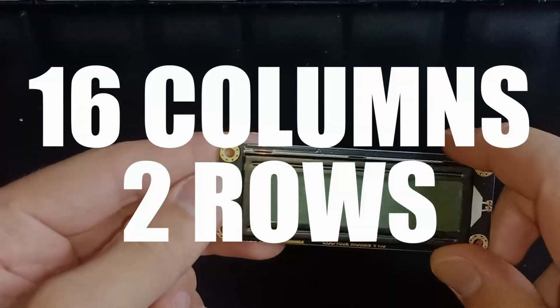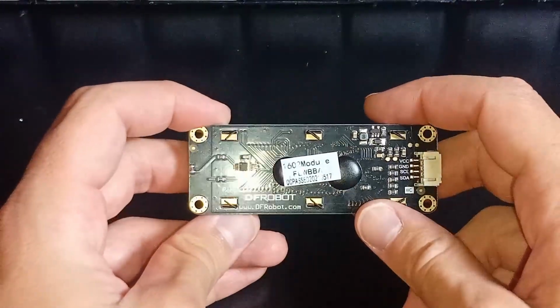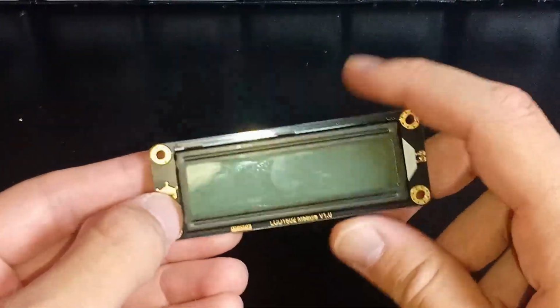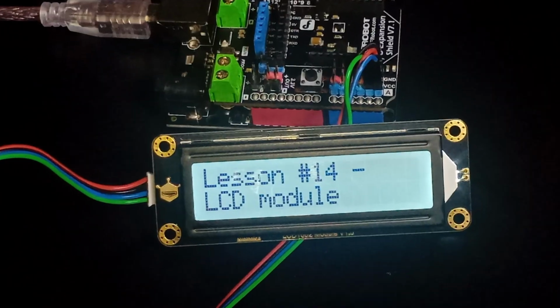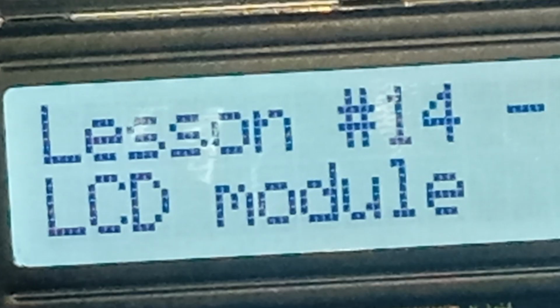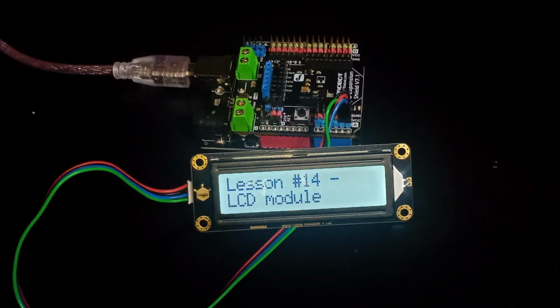1602 means 16 columns and 2 rows. So a 16x2 character LCD can display up to 16 characters per line, with 2 lines total. Now, even though we call this a character display, each character is not just a single block. If you power up the screen and take a closer look, you'll notice that every character is made from a 5x8 grid of tiny dots, also called pixels. By turning different pixels on and off, the LCD can form letters, numbers, and symbols. Once you understand this, a lot of limitations and possibilities start to make sense.